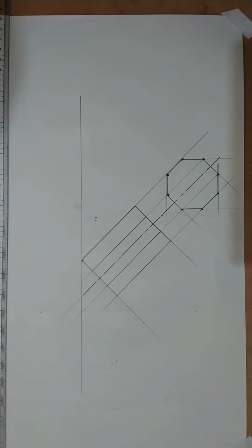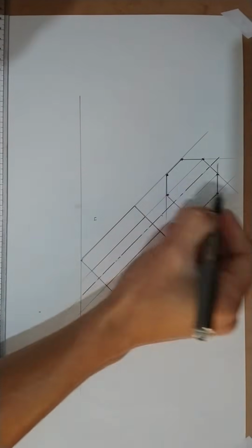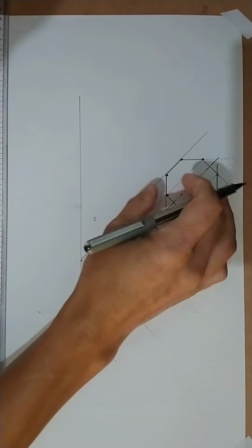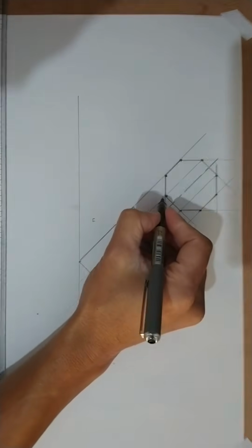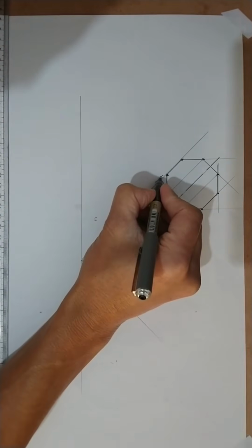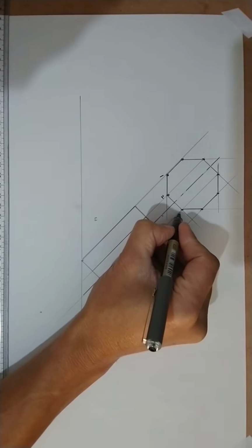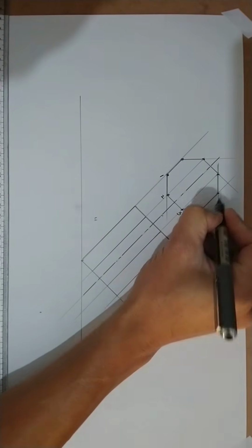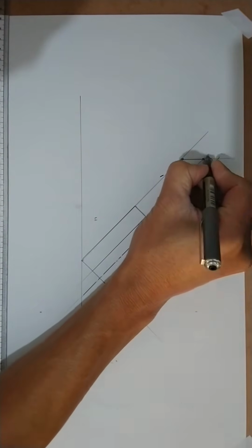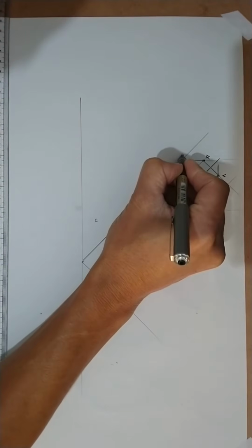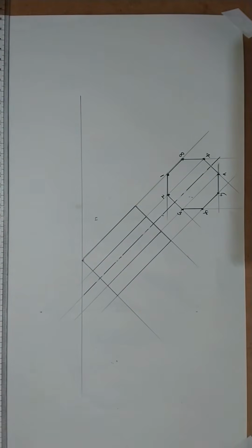What is very important now, when you work with solids, is that you have to number your corners. So you can start here, always label it here, and then it projects down. So you can start anywhere. I'm going to make that my number 1, and I'm going to go in an anti-clockwise direction. Number 2, 3, 4, 5, 6, 7, and 8. Those are my 8 points, right?